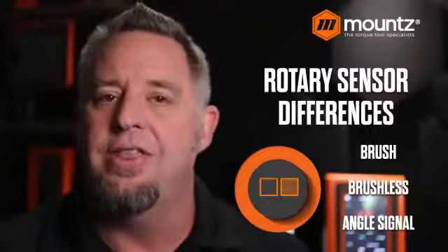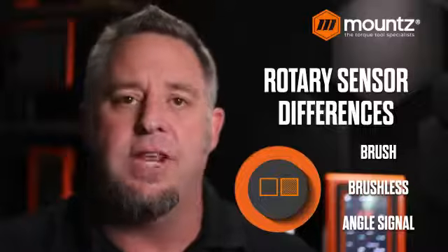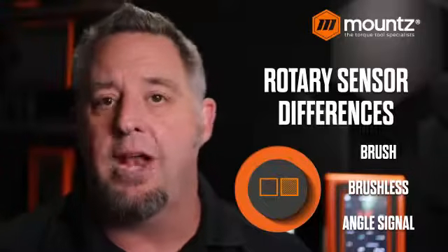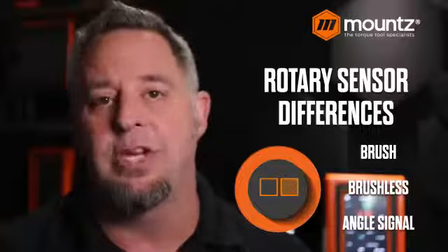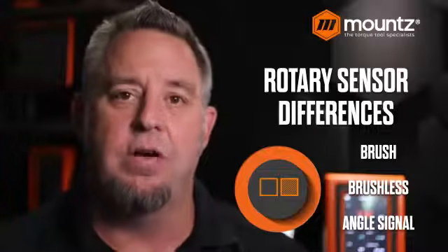And so there are a couple different ways that we can do that. One would be the first movement test, where you put your fastener in the actual fastening rotation, and we move that about 5 degrees, and we can see what that value is. That's going to be representative of the torque that was applied.